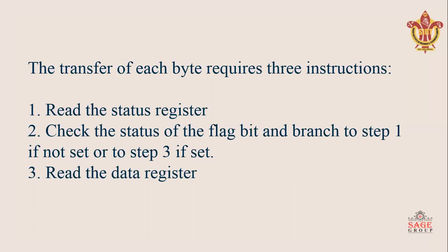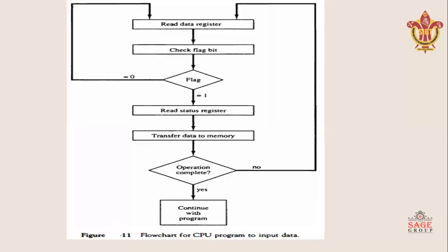Whenever the data register becomes empty, the data accepted signal from the interface to the input-output device will be disabled, and then the input-output device will send its data through this data bus. That means the data bus and data valid signals will be enabled whenever the data accepted signal is disabled.